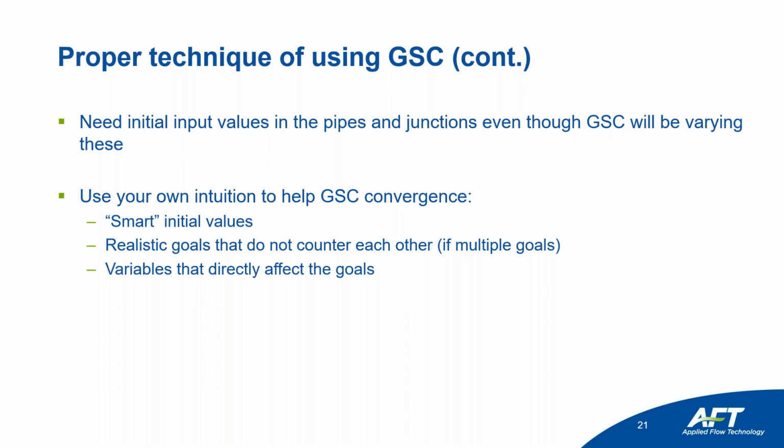Make sure your variables directly affect the goals. Again, the goal must be a function of the variable you are changing. And lastly, this is pretty important, the number of variables should equal the number of goals. 0 degrees of freedom is the key.